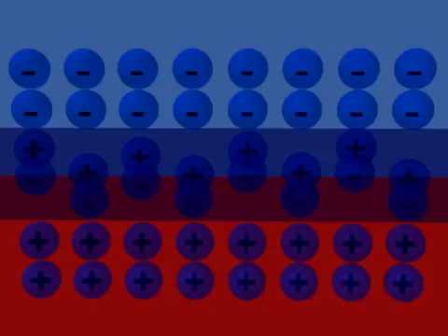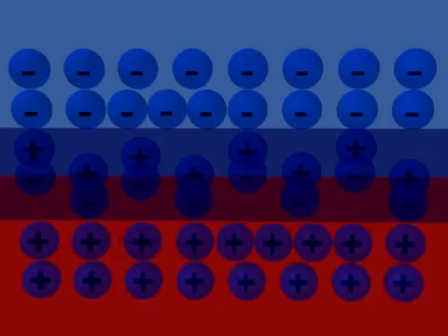However, if photons hit the silicon layers, electron-hole pairs will be created. If this happens in the electrical field, electrons are moved to the N-doped layer and holes are moved to the P-doped layer. The system will fall into a state of imbalance because of an excess of electrons in the N-doped layer. The corresponding holes can be found in the P-doped layer.